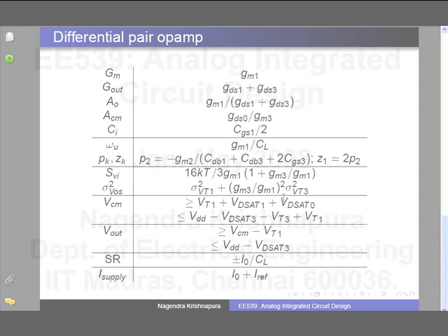Whatever you do to the aspect ratio, it will not change the GM. It's only dependent on the bias current, like a bipolar transistor. So, once it goes into subthreshold region, you can't reduce the current anymore without reducing GM. Okay, that's the main point. Now, the other point is also that, of course, the parasitics have increased and it may affect you. Maybe it will form a dominant part of the load. But even if that's not the case, you can't do this indefinitely.